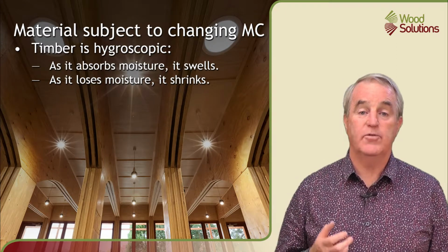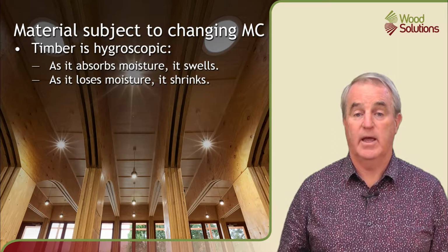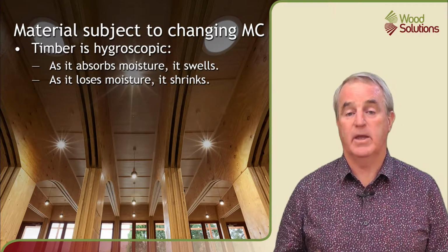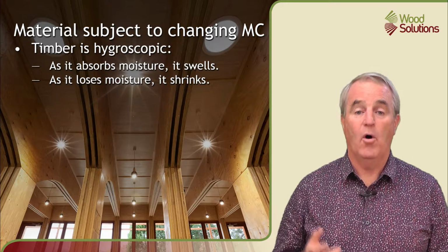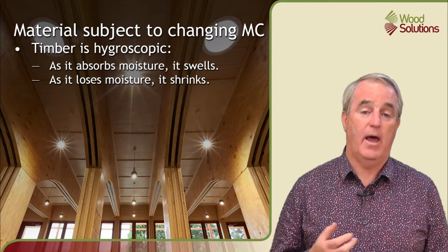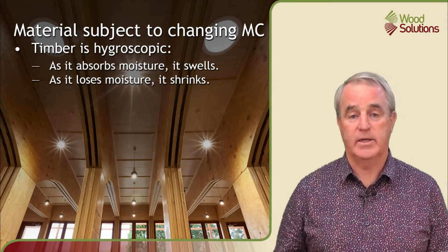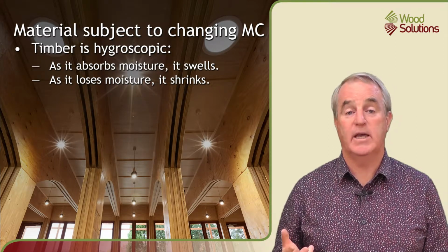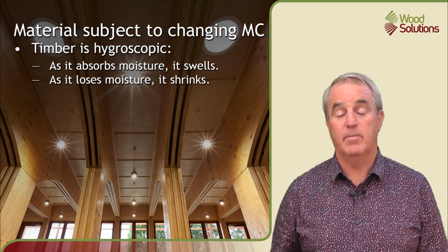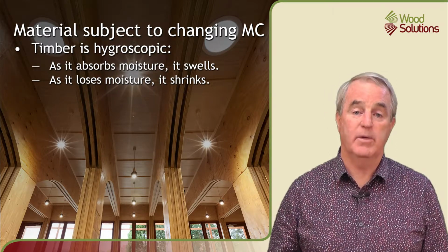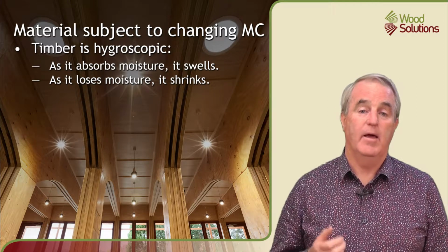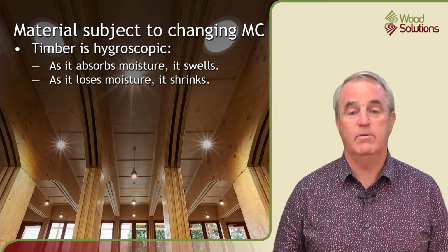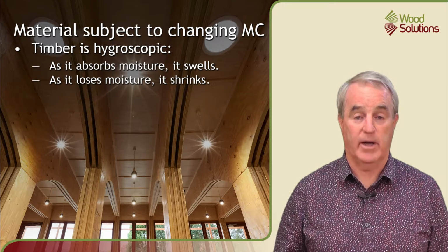Material will be subject to very high and changing moisture content and dimensional change if it is installed in spaces with high humidity, such as pool enclosures, or with low humidity, such as in a home with large heaters or air conditioning systems. In applications like flooring, the timber's moisture content as it is installed is very important and should be discussed with the builder or the floor layer. Placing timber in changing moisture conditions can generate numerous problems for timber floors, cladding and similar products.